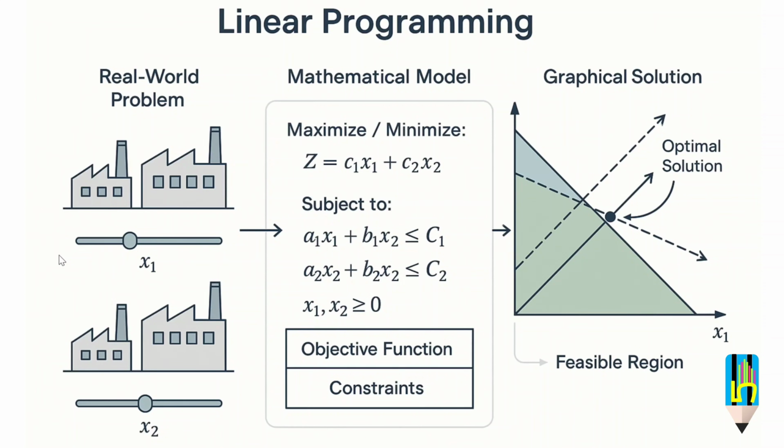So what we have to do here is linearize the reality, which means simplifying the system drastically. We must pretend that the cost of the pipe area is linear, and most importantly we must ignore the true non-linear head equations like Hazen-Williams.